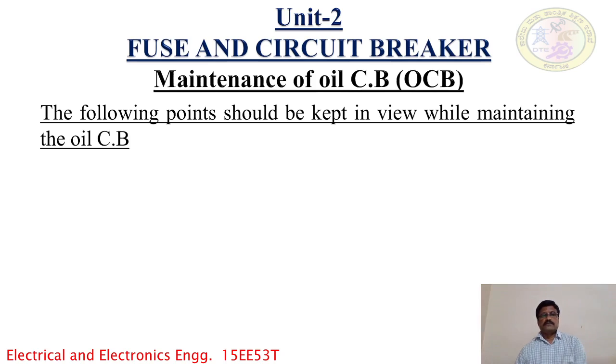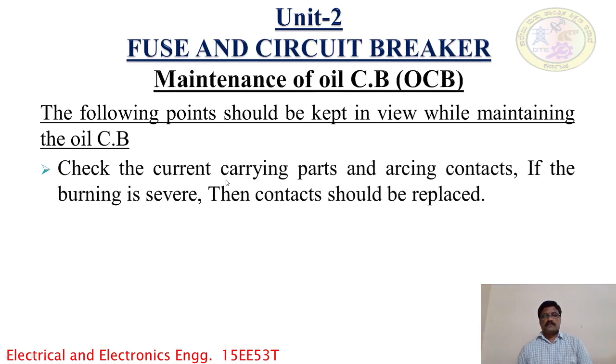The first point: check the current carrying parts and arcing contacts. If the burning is severe, then the contact should be replaced.